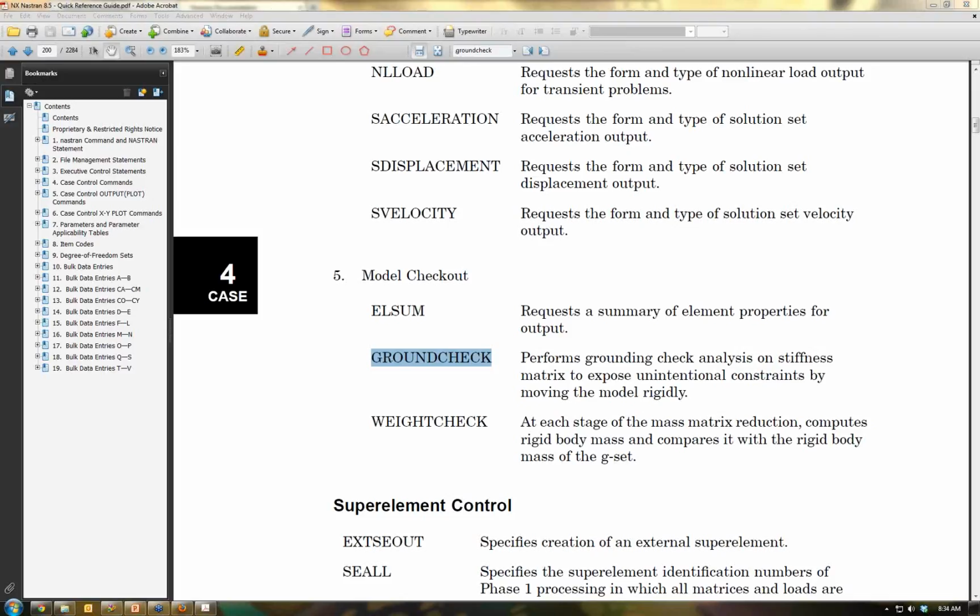When you've got this plane up in the sky and you need to perform some vibration, it's not fixed to ground. It's not a cantilever beam rigidly attached to the wall. We want these kind of floating, free vibration checks. And so when we perform this ground check, when we see the word pass, we know that we're truly ungrounded, a truly free analysis. But that's not to say that we can't use ground check on models that are going to be constrained for a static stress analysis. I'll start out with that, and later on in the webinar we'll move to a free vibration analysis.